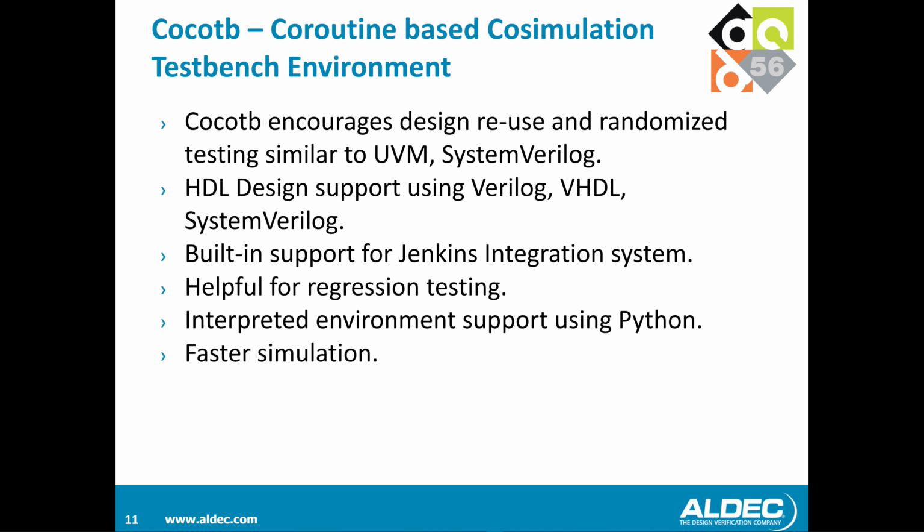Now this is what CocoTB is. It encourages design reuse and randomized testing similar to UVM and SystemVerilog. It has HDL design support with Verilog, VHDL, and SystemVerilog, meaning a user can have a design based on Verilog, SystemVerilog, or VHDL, and do the verification using Python CocoTB. Nobody has to do the design in Python as well. You can still do your design using HDLs and verify it using CocoTB.